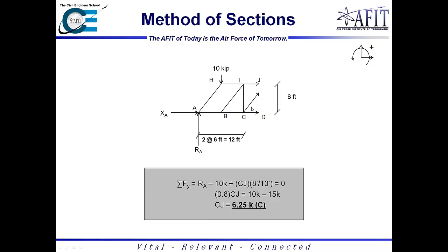This is the same exact answer that we got using the method of joints. It's just that the method of sections streamlined this whole process. The method of sections is ideal for members in the middle of a truss that you have to solve for, especially if the method of joints would take a prohibitively long time on an exam. However, there are situations where you will be forced to use the method of joints, particularly if cutting the member would violate one of the 3 rules, or if the member was right here, like A sub H. Then the method of sections wouldn't make any sense.